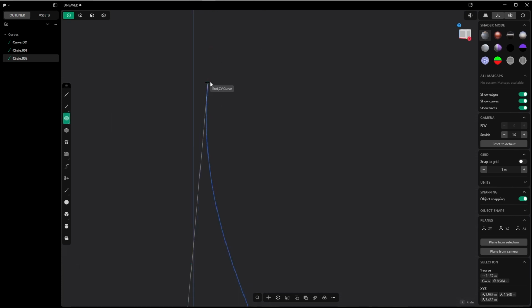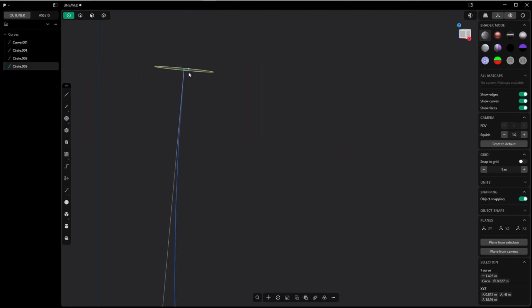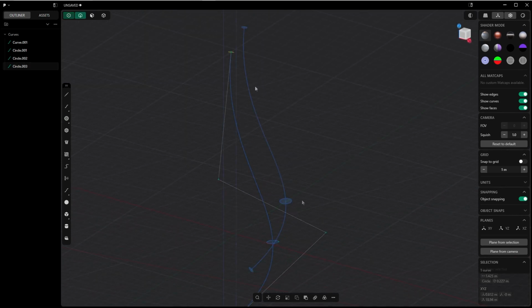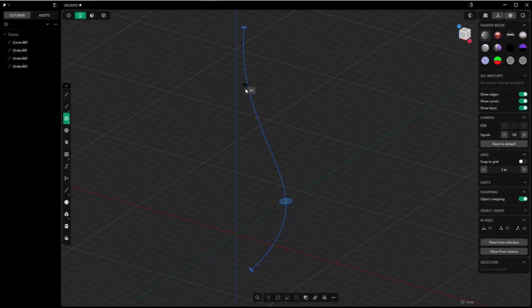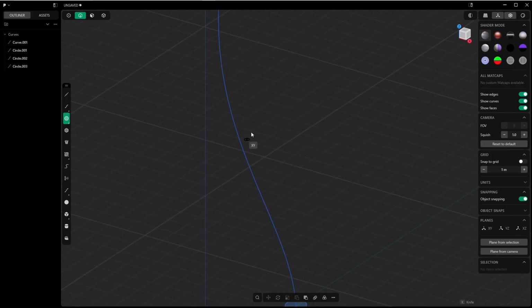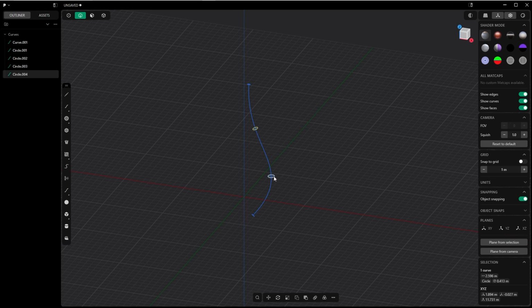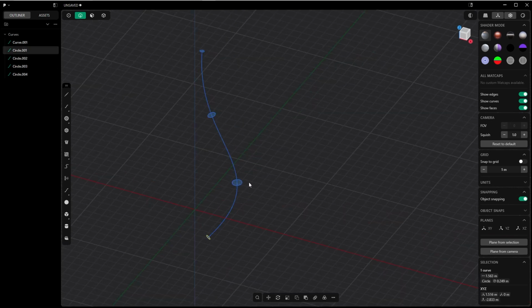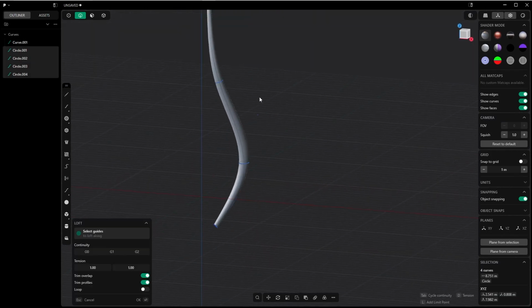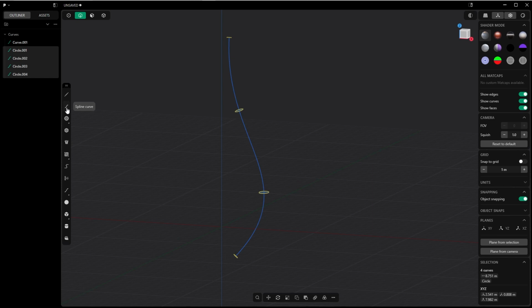The third circle can be here at the top. And this one can be again smaller than the second one and binormal. So let's see what we have. That looks okay. I said 3, but I have to have 4 center circles. Let's create one here. And this one should be slightly smaller than this one, but bigger than the one at the top. And if we loft now, we get something like this, which is okay,